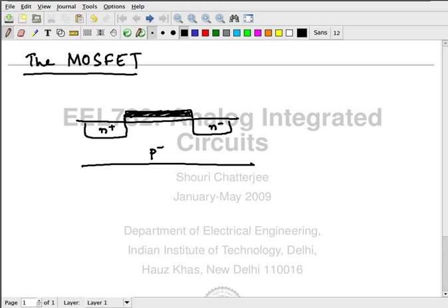Student: Poly will behave as a gate itself. Yes. But won't this doping affect the characteristics of the polysilicon itself? This is how it's done, so all that is taken into account. It's taken into account that the characteristics of the polysilicon will get altered, etc. In any case, you want the polysilicon to be conductive. So if you introduce N plus into it, fine. It's even better. Okay, so this is called the self-aligned process. This is what we use all the time.